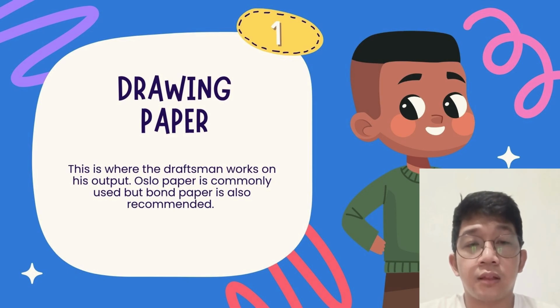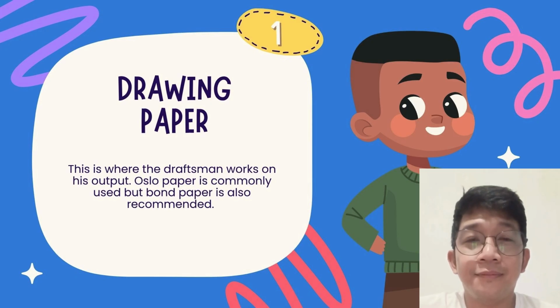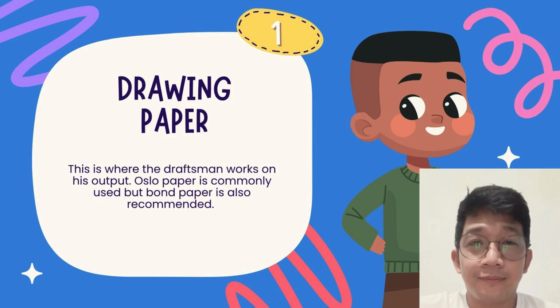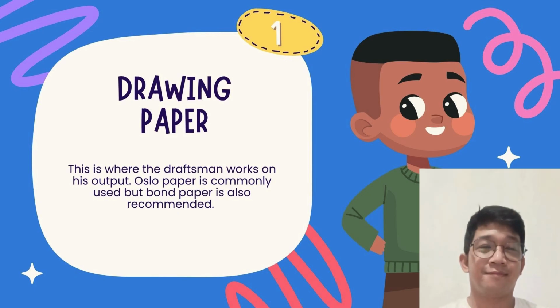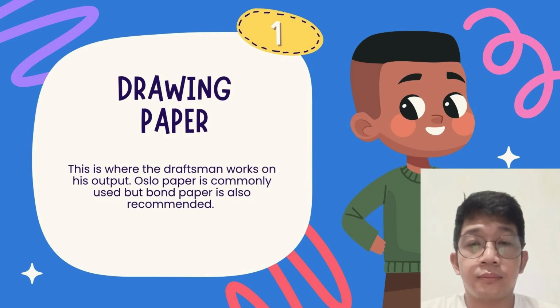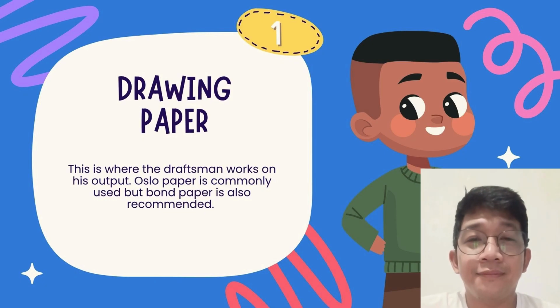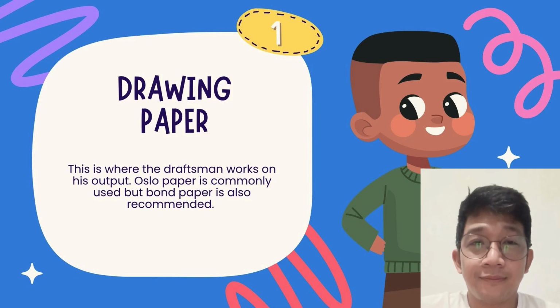These include vellum paper, a smooth, translucent paper that is durable and ideal for ink or pencil drawings. It allows light to pass through, making it suitable for tracing and reproducing designs. Tracing paper, a thin, transparent paper used to trace existing drawings or transfer designs to another surface. Blueprint paper, special paper used in traditional blueprint processes, where drawings are reproduced in white lines on a blue background. Detail paper, a semi-transparent paper used for making detailed sketches or preliminary drawings before the final version.